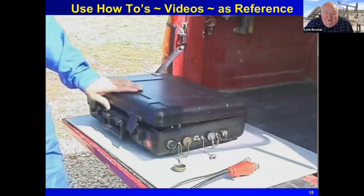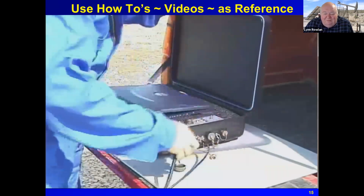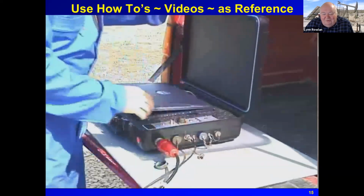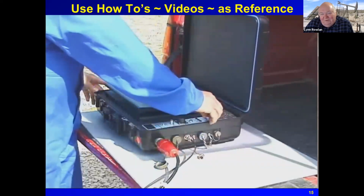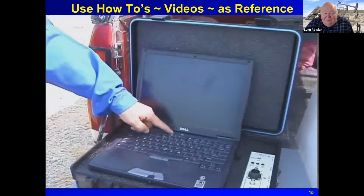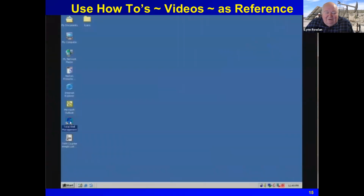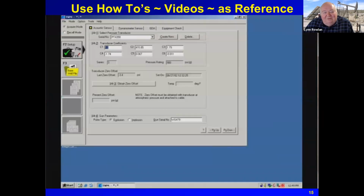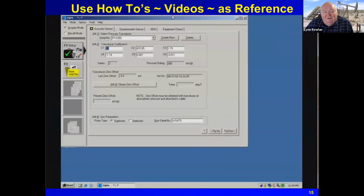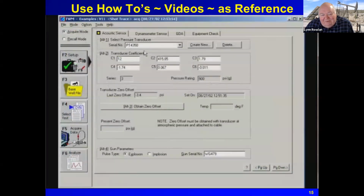Now he goes back to the laptop at the back of his truck, and he attaches a microphone cable to the wired well analyzer, and then he also attaches the cable for the pressure transducer to the well analyzer. Turns the well analyzer on, starts the software, and then he would load the software. This is the TWM software, and here he's going to go and perform a zero on the equipment. And so that's the steps to fire a shot.